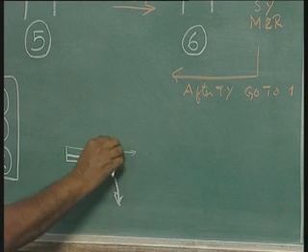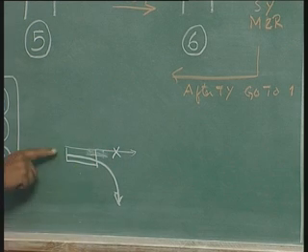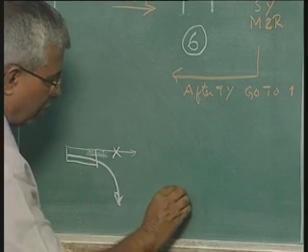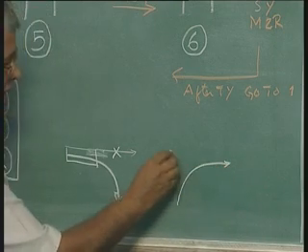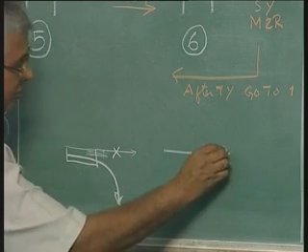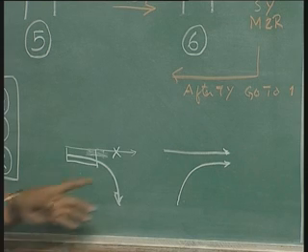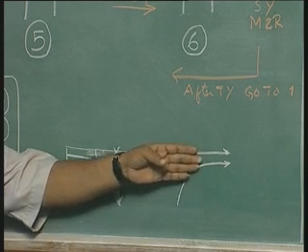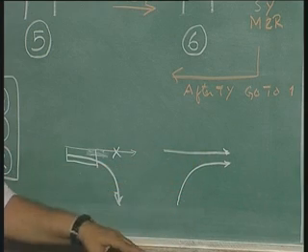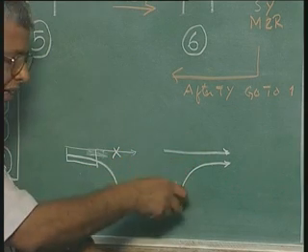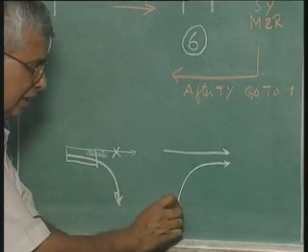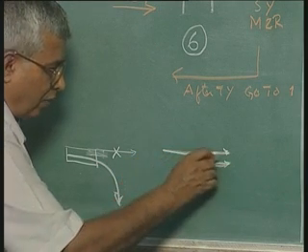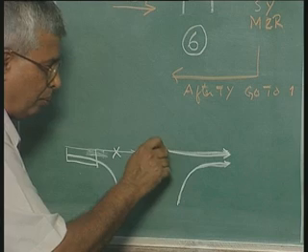I need not stop this for letting this on. On the other hand, when I am turning from here to here, I cannot let this happen, because we do not know how well these lanes are defined. Supposing these lanes are not well defined, there is a possibility that this traffic coming from the side road into the main road may collide with the traffic going directly from left to right on the main road.